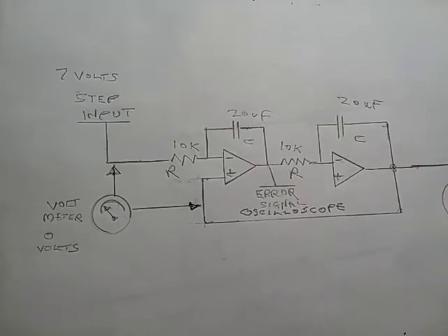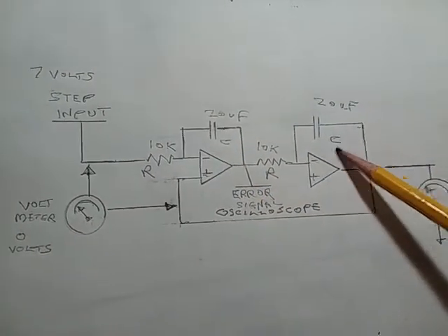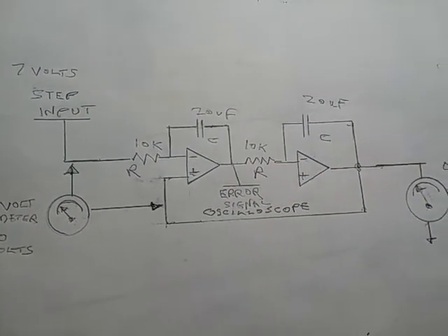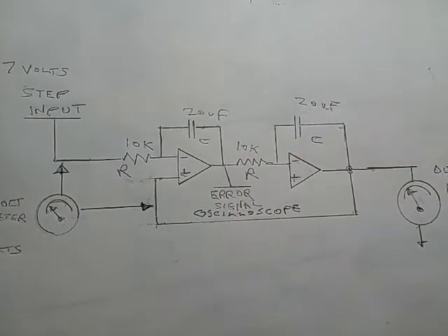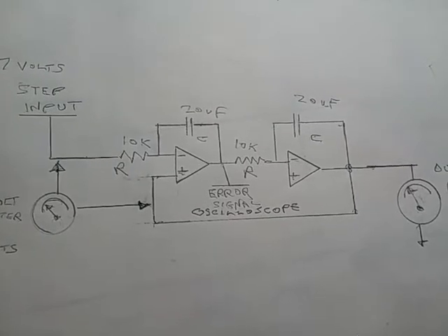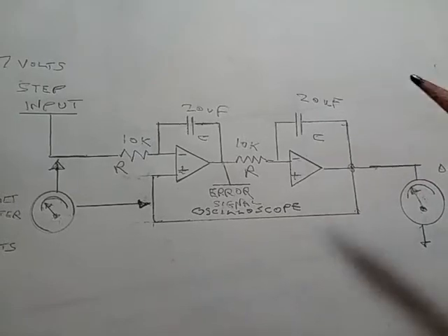Again, in this case, you have an error detector and an output motor. In this case, the motor is an integrator, as the output is the integral of the input signal, which is typically a ramp.